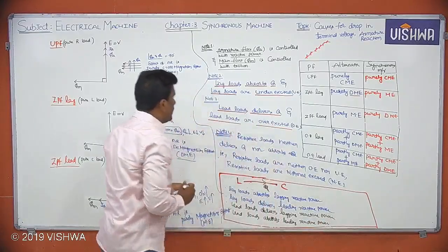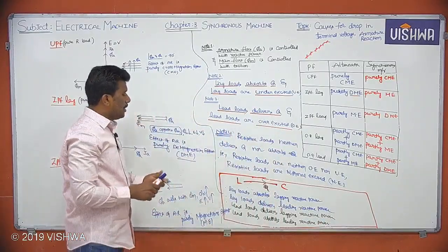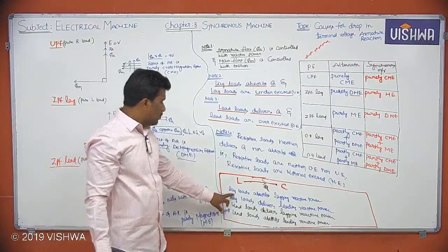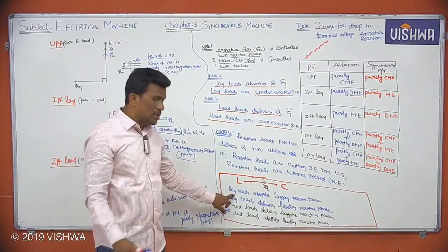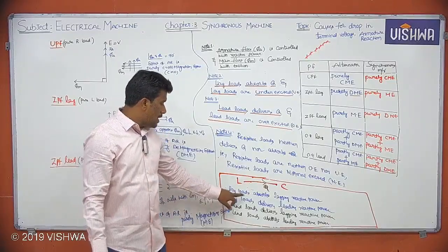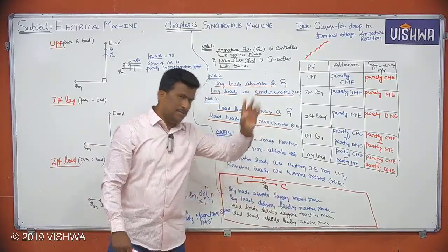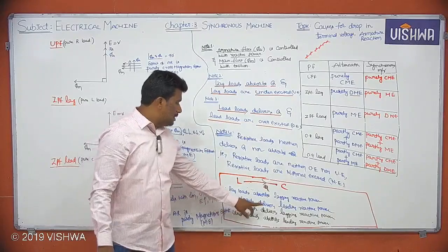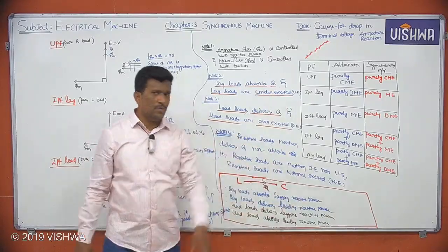So if you want me to write similarly, generally in terms of lag, what does it mean? Generally inductive loads. Let me complete the statement. Inductive loads absorb lagging reactive power. Inductive loads deliver leading reactive power. Both statements are correct.